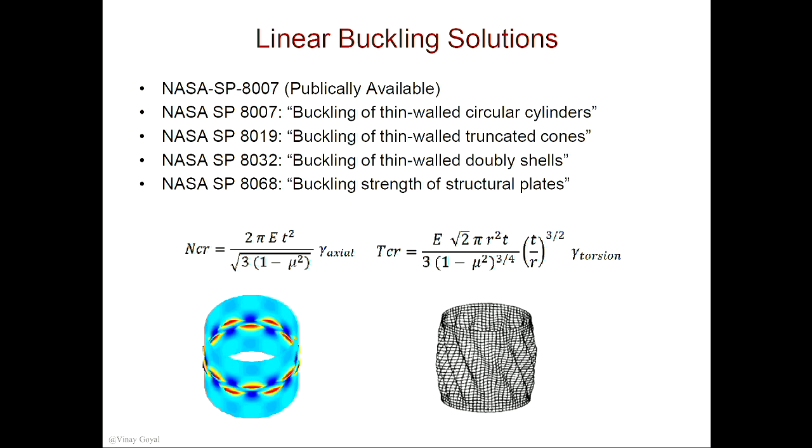you see this gamma here? Yeah? You see that gamma? Let's face it, it's a fudge factor. It's to get your analysis to match the experiments. What people have done is an extensive amount of experiments, and since a linear buckling solution will never match the experiments, why not just use a database to adjust the analytical solution, the linear buckling solution, and get it to match the experiments? That's one thing that people have done, and that's what these gammas do. They're called knockdown factors.